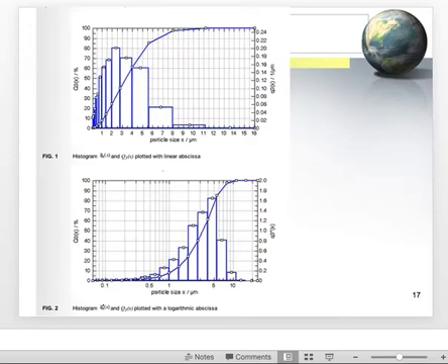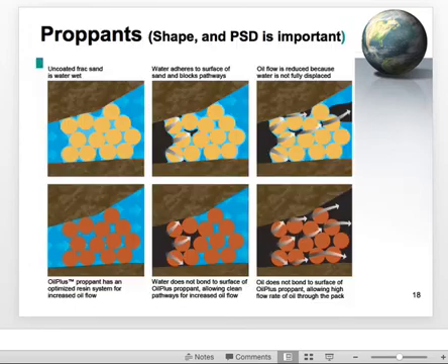And again, there are a couple of different other ways of plotting this out. So, some examples of why we utilize this. Proppant: we know that we would like it to be spherical particles. We'd like it to be narrowly sized. If I had a distribution of particle sizes, I would plug these open spaces with smaller particles, and my fluid flow would be impacted.